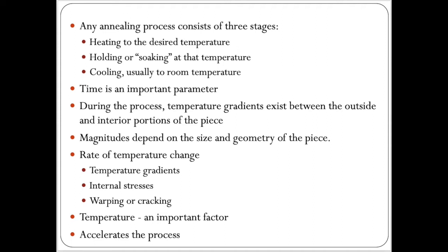If the rate of temperature change is too great, temperature gradients and internal stresses may be induced that may lead to warping or even cracking. Also, the actual annealing time must be long enough to allow for any necessary transformation reactions. Annealing temperature is also an important consideration. Annealing may be accelerated by increasing the temperature because diffusional processes are normally involved.